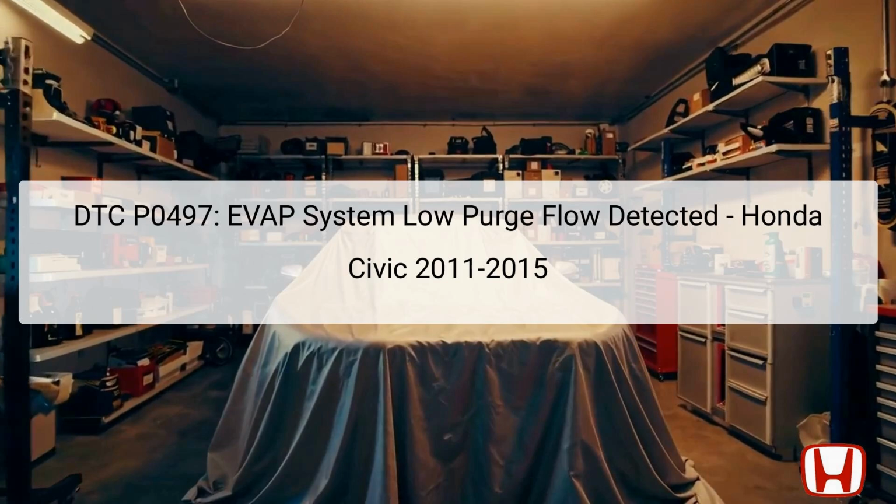The Diagnostic Trouble Code, DTC P0497, signals that there's a low purge flow in the Evaporative Emissions Control System, EVAP, of the Honda Civic models from 2011 to 2015. This system is crucial for capturing and recycling fuel vapors from the fuel tank, helping to prevent harmful emissions from